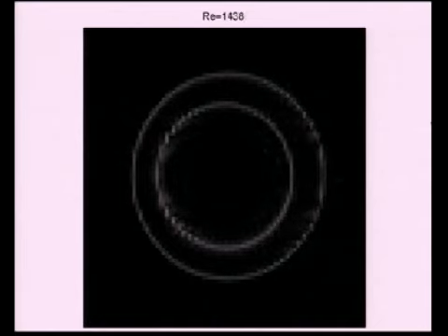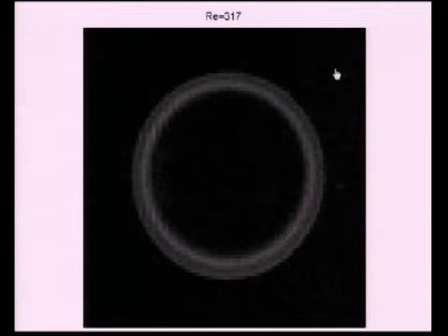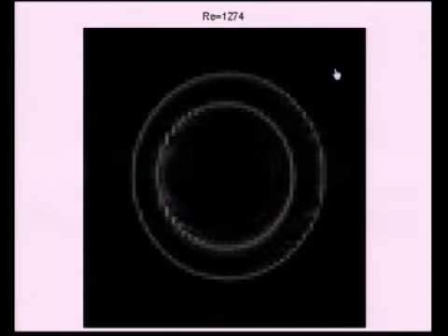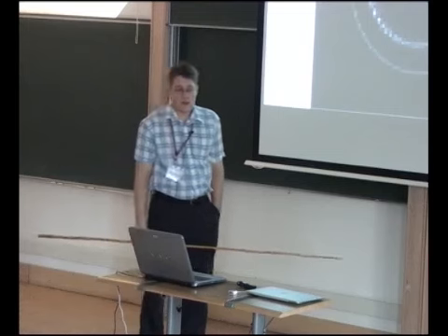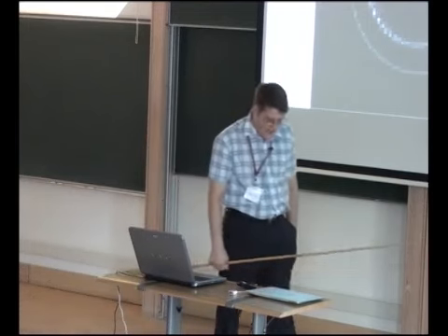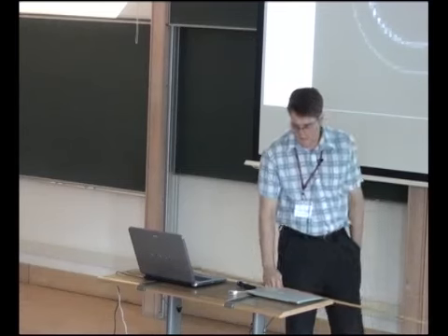So we increase the Reynolds number. You can now see the start of the shear layer in the middle. Reynolds was increasing: 800, 1,000, 1,200, and so on. And I don't know if any of you noticed that. I'll just play it one more time. But as I increase the Reynolds number, my shear layer first appears, but then it becomes asymmetric. It goes over to one side of my pipe, and I think it comes over to this side here.